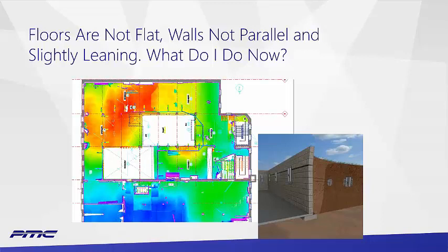It really depends on the needs of the project. If you are on a construction team and you need to verify fits and routings and things extremely precisely, your best bet is to not create a CAD model and simply stay in the point cloud, because you are never going to create a CAD model that is as accurate as the scan data was. It's always going to get worse.